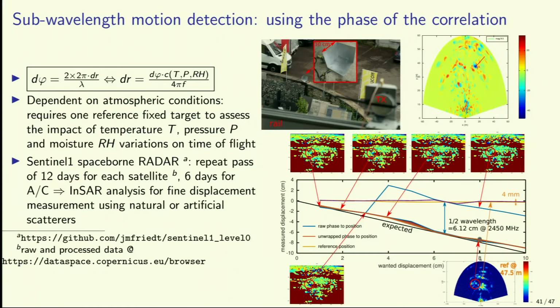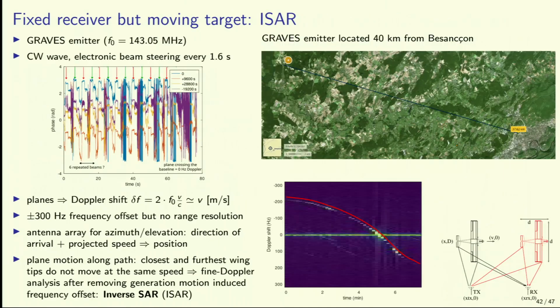And finally, the last thing you can do: we've been discussing so far only magnitude, but a radio frequency quantity is vector information. It's got a magnitude and a phase. So if, rather than just using the magnitude, you look at the phase of each one of these targets, you can get a range resolution much lower than the inverse of the bandwidth, and that's given by the interferometric measurement, the phase difference. The phase difference has an ambiguity of 2 pi, which is the two-way trip of a wave, but this is actually what is used for landslide monitoring, where you're looking at the phase information. I will not get into the details because I'm running out of time.